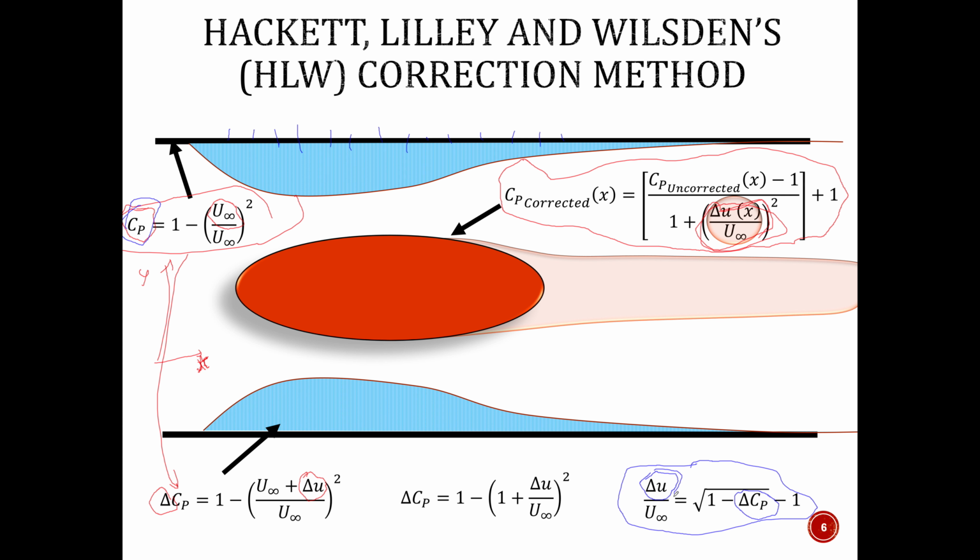If you have an airfoil or any bluff body, you can use this equation to put it in here, and then you can get the CP variation across the object. Once you know CP, you can also calculate lift and drag measurements. So this is basically what they came up with.